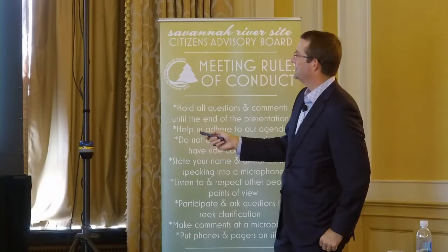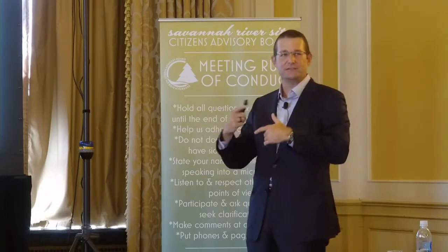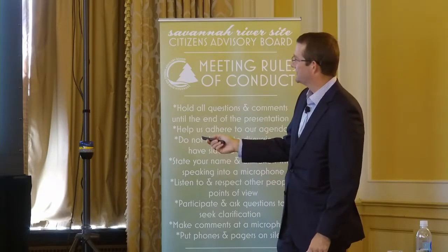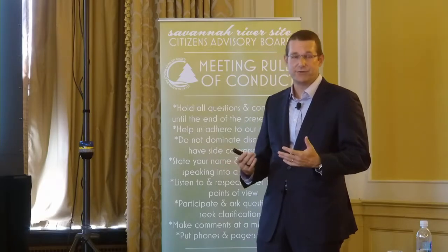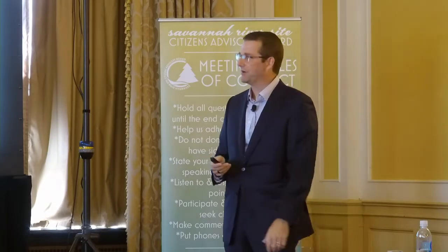Each one of these, as you notice, is indexed so that it is continuously in close contact with the paddle next to it. So those paddles are effectively self-cleaning. It's very close tolerance, and you'll notice it's also very close tolerance with the wall. Very high rate of shear, so within about 20 or 30 seconds of residence time, you go from a completely dry, unwetted material to a very smooth, flowable, homogeneous product.